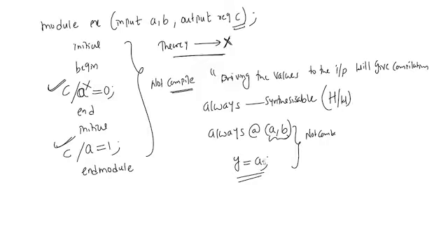So for this you need to write always @(A) y equal to a, which will compile because only one sensitivity list is there. But this sensitivity list you are not using anywhere. The sensitivity list is nothing but: if there is any change in those inputs, then there is a change in the output.